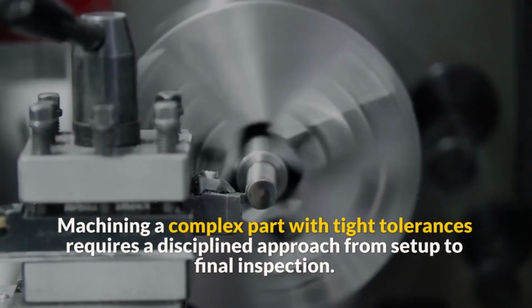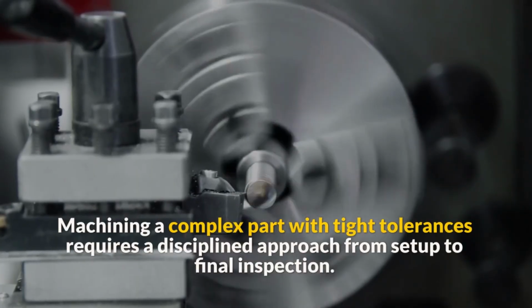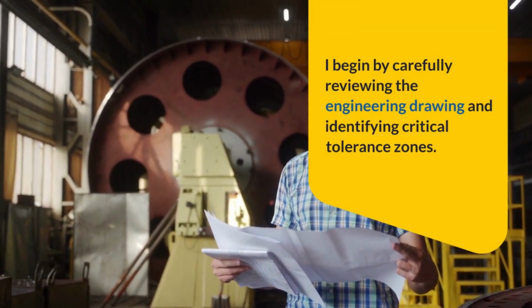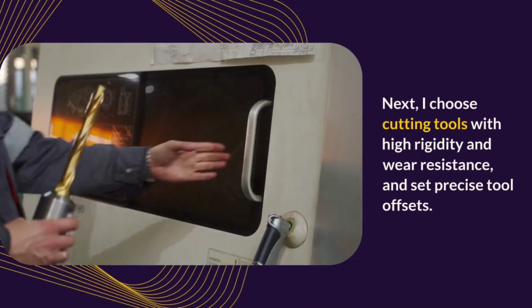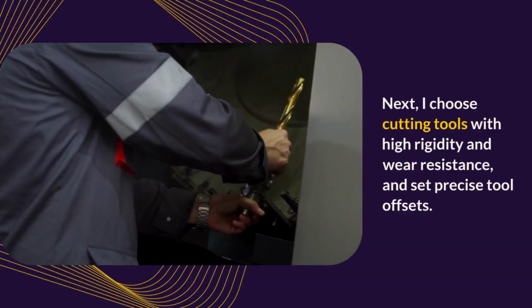Machining a complex part with tight tolerances requires a disciplined approach from setup to final inspection. I begin by carefully reviewing the engineering drawing and identifying critical tolerance zones. I then select the appropriate CNC machine that can deliver the required precision. Next, I choose cutting tools with high rigidity and wear resistance and set precise tool offsets.